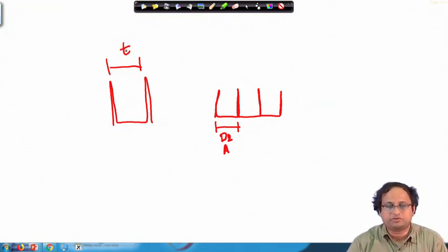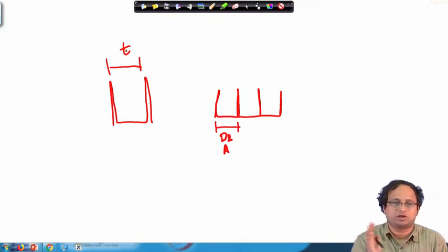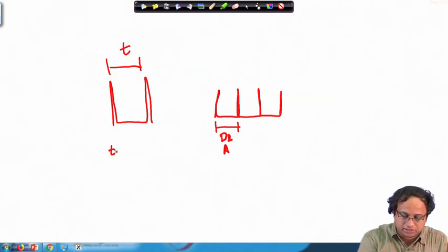So if t is equal to 12 clock cycles, you immediately know that it is two ones, one after the other. That means there are no zeros in between. On the other hand, if t is greater than 12, then you can understand that there are n zeros in between.